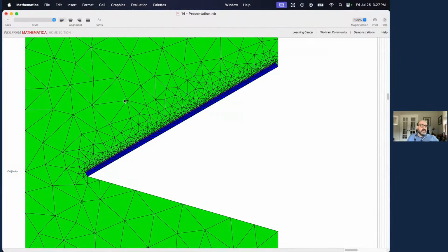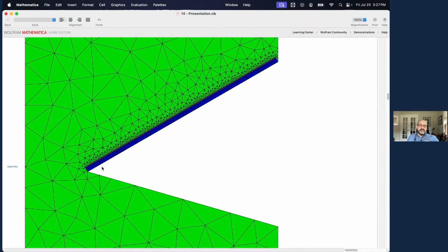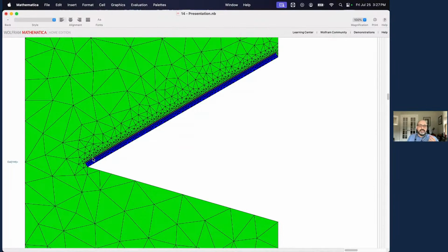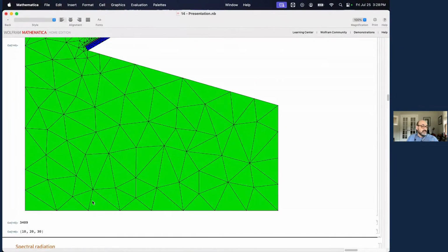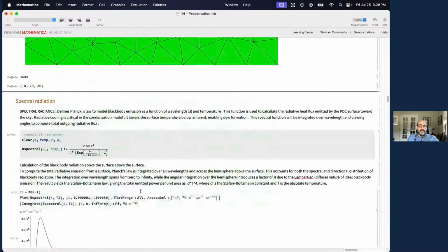Since I already have my Navier-Stokes solution, now I take another mesh and I inject the results into my new mesh. The results that I inject are only the most important ones that I care about. It's just the area next to the plate, right? And the plate itself. And that's where I get a better refinement. Now I went from 70,000 elements to only 3,000. This is very important because now you're reducing the solution time very significantly.